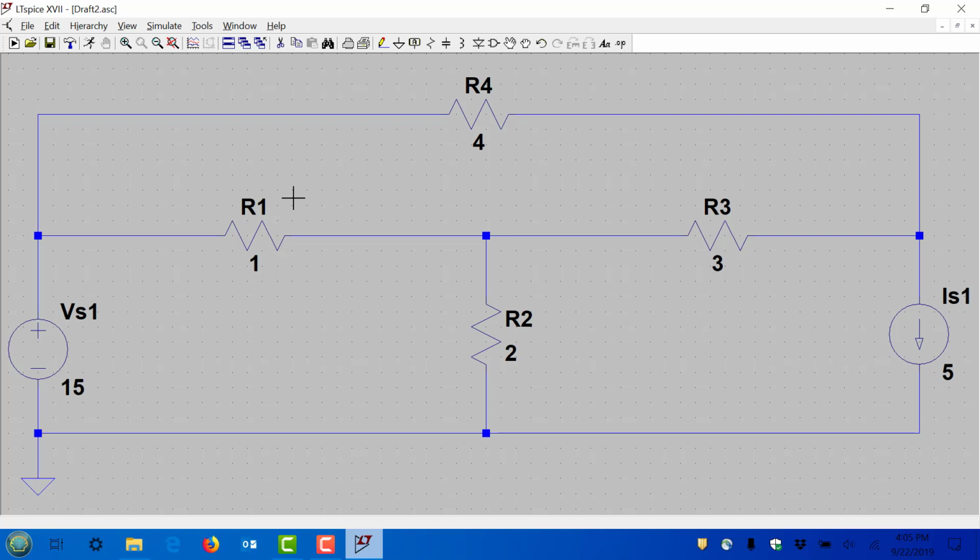The next thing we know is that they have the values. So these values have to be entered. If you just leave in the default, your simulation won't run. So we noticed that. But what we haven't seen is that behind the scenes, the simulator LTspice has already made a listing of all the components in the circuit and their connectivity. First of all, it actually numbered all the nodes.